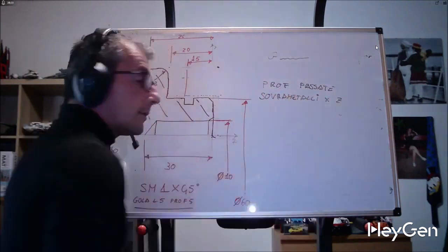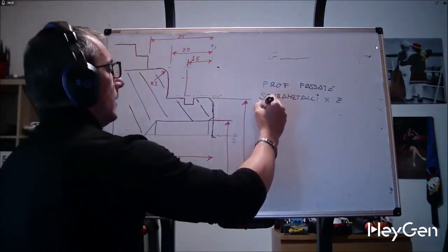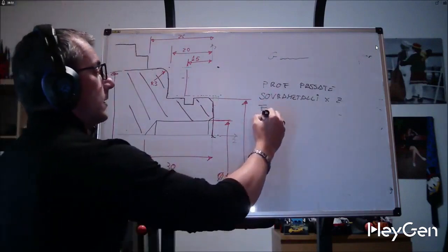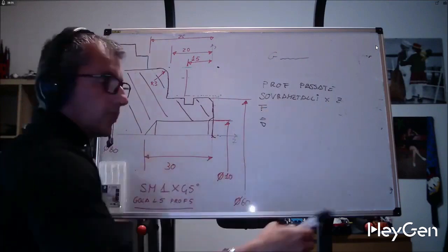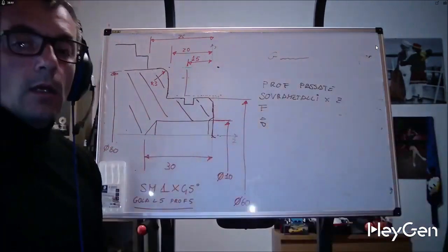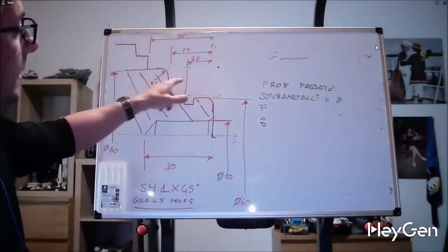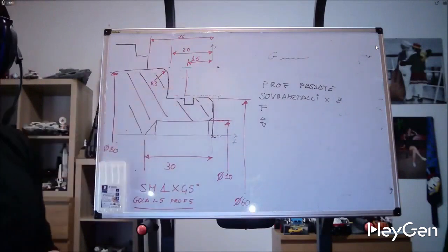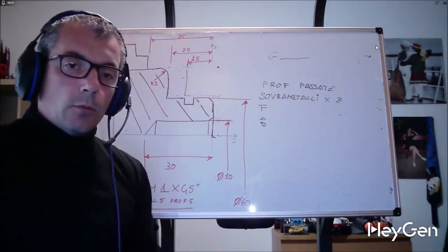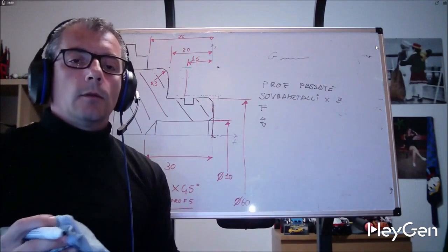And let's see the so-called disengagement distance, that is every time I rough, how much I need to disengage before returning. Given these simple codes, what does the machine do? It will read the finishing profile and adjust all those passes that we have set. I hope not to bore you too much, but I also don't want to rush. So I prefer to explain things gradually.